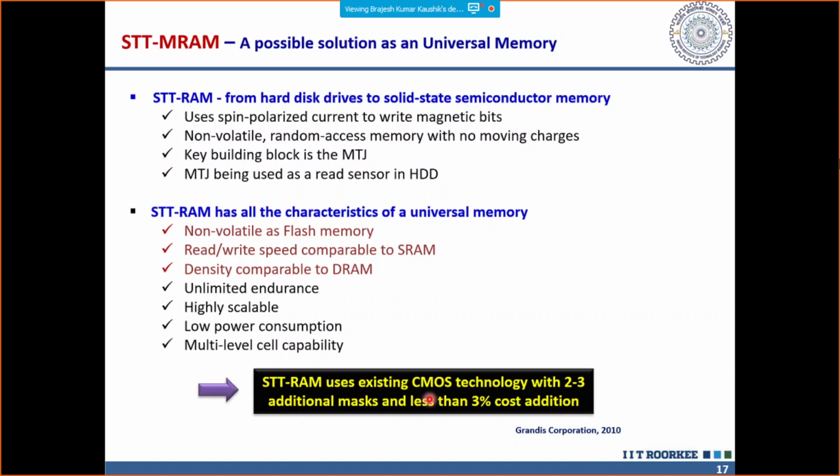Now STT-MRAM, as I said earlier also, the spin-based MRAMs have now become a universal memory solution. It's not that STT-MRAM came up recently. Your MTJs especially, which is one of the important constituents of your STT-MRAM, have been there for a very long time. In fact, your MTJs were being used in the read sensor of your HDDs, hard disk drives.